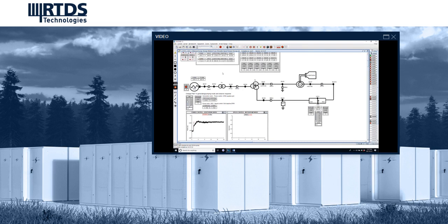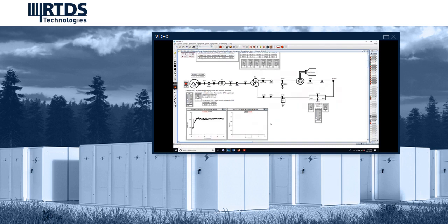The operation of the pump storage system in pumping mode will be demonstrated. In pumping mode, the DFIG speed is controlled by the rotor side converter. The power reference set point is used to determine the governor output to adjust the gate position. The power flow is from the grid to the turbine. The DFIG response to a step change in the power set point will be demonstrated.